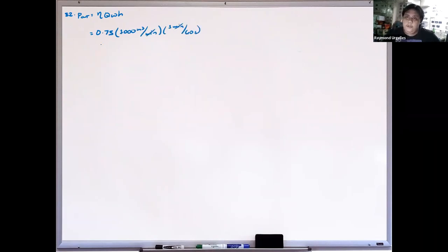Okay? So then this is multiplied by, so again, let's use 9.81, para kilowatt kaagad yung makuha natin. So kilonewton per cubic meter. Okay? So then we have an effective head of 100 meters. Pag sinolve ito, this will be kilonewton meter per second. So that's kilowatts. So you should be able to get 12,262.5 kilowatts. Okay? So kaya yung sagot natin dito is letter C.